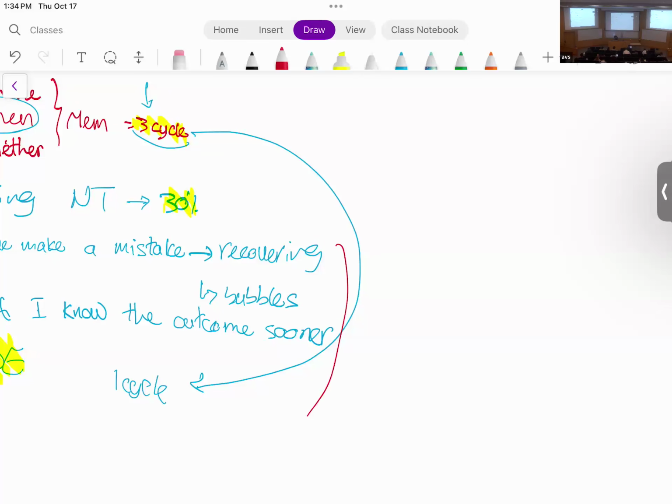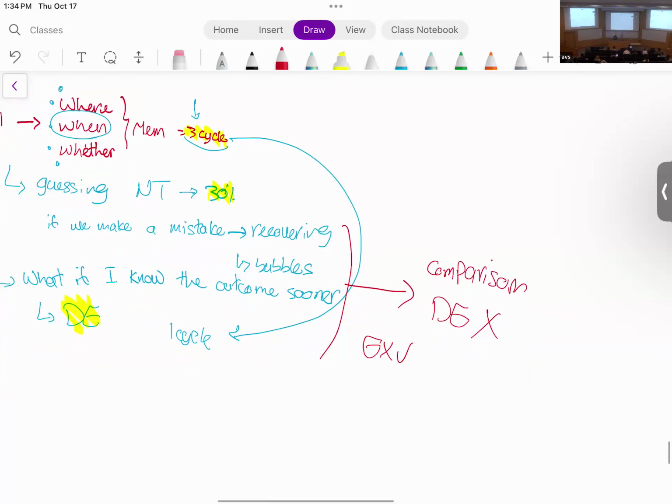So since the comparison happens during the decode, what used to be fixed by forwarding things to the execution stage no longer works for the decode stage, because the forwarding is not happening during the decode stage. So what we do instead is we stall for 1 cycle and then continue doing what we used to do.